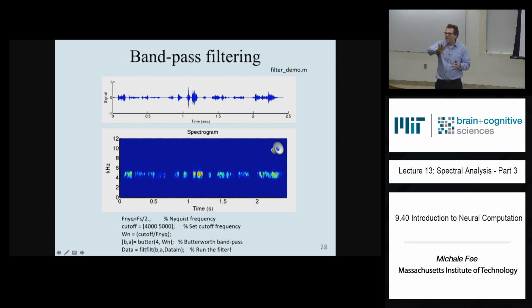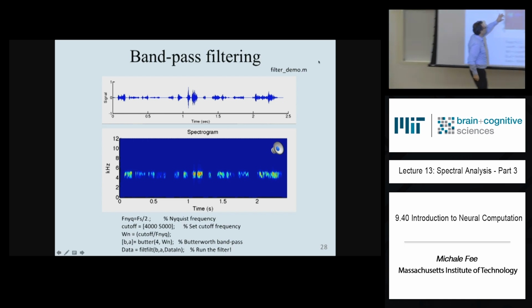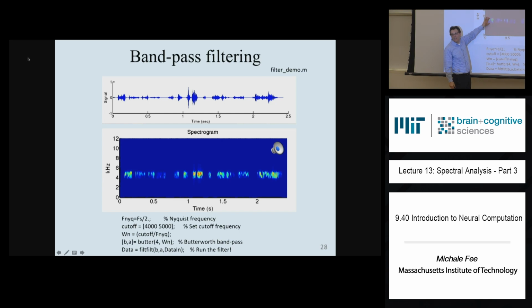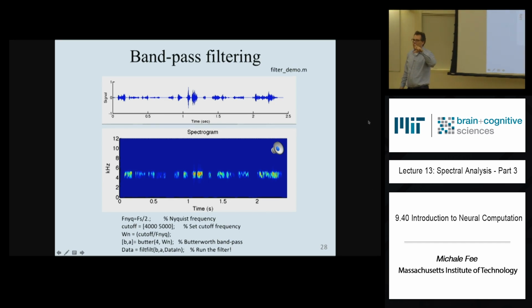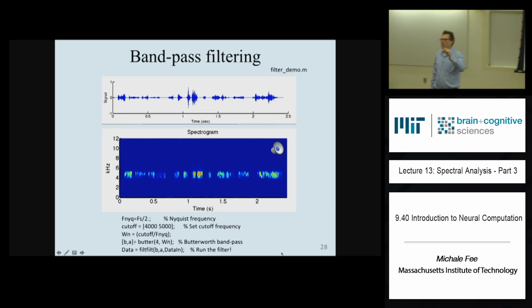You could make what's called a band stop filter, where you suppress frequencies within a particular band. Put that band stop filter at 60 hertz. The problem is it's very hard to make very narrow bandstop filters. So how would you, we learned this in the last lecture, how would you get rid of a particular signal?